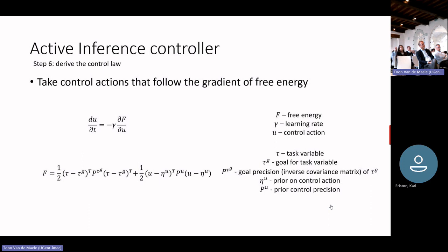Next one is that imagine that you already know what kind of force you wanted to use, or from prior learning, you kind of know that this task might take 10 Newton, but just vary around it. So then you can just put an artificial thing around it and put a tighter bound on it. If you don't know the control action at all, like you're completely new to the system, then I would recommend putting this as 0 and loosening this up, with a low value for PU.